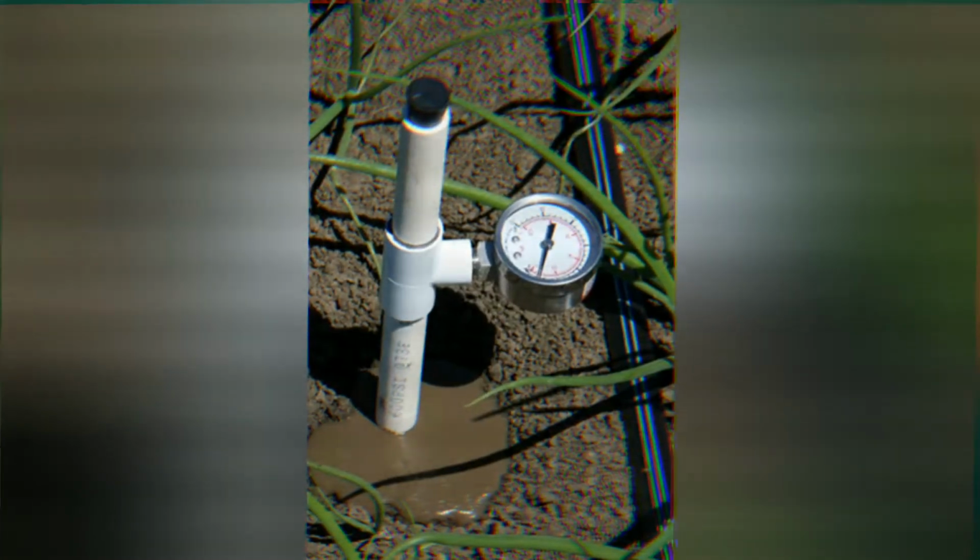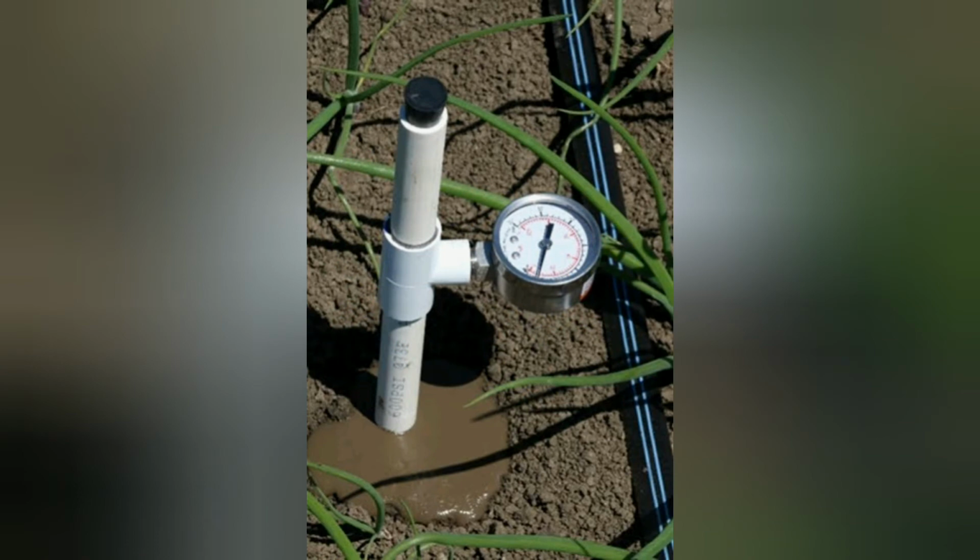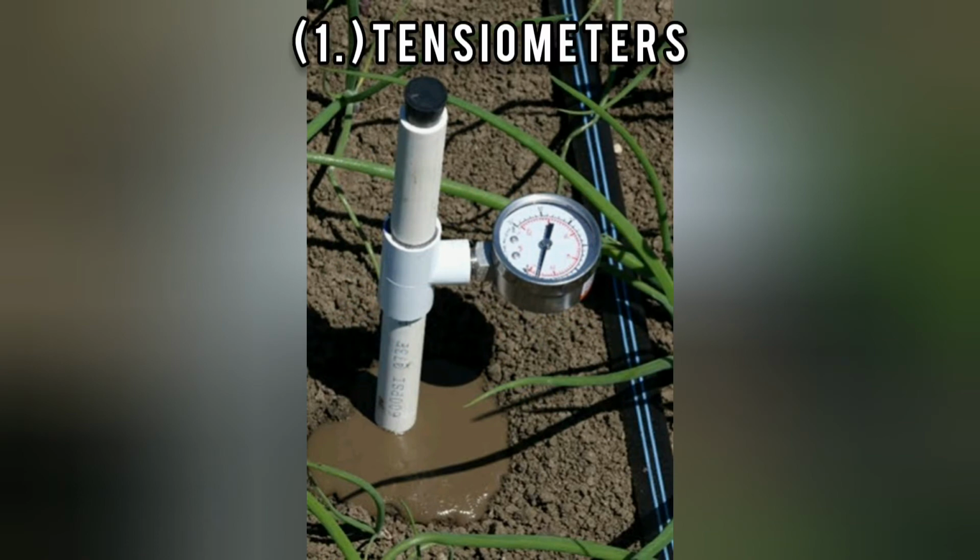There are three subtypes of measuring soil moisture. The first one is the tensiometer. Tensiometers measure how strongly water is being held by the soil. As the soil dries out, moisture is more strongly held to soil particles and less available to the crop. Tensiometers can be used to determine when moisture stress occurs and thus when irrigation should be started.